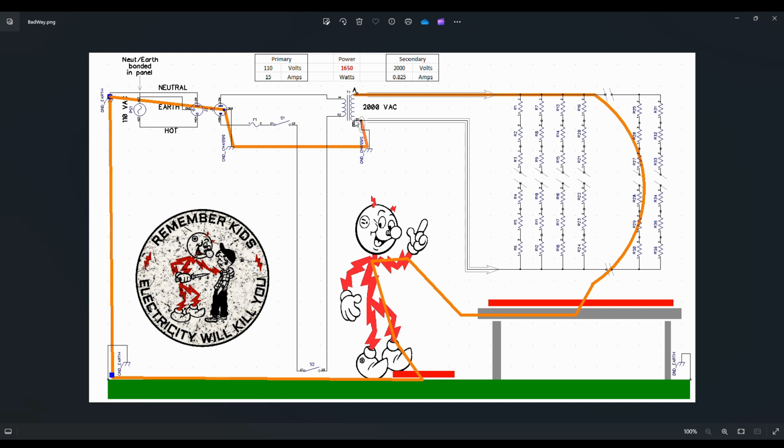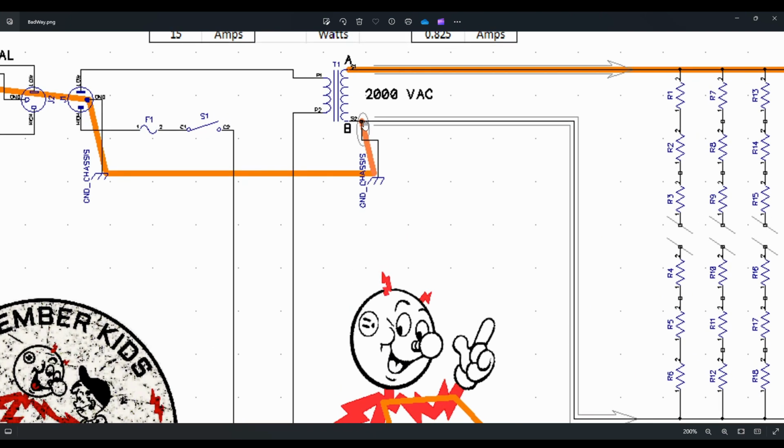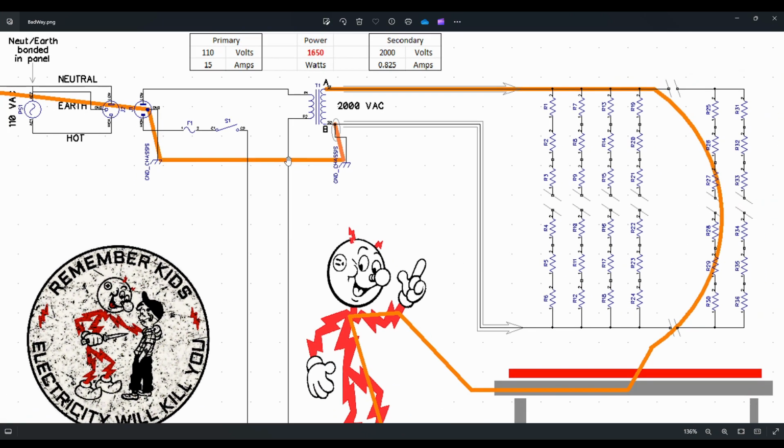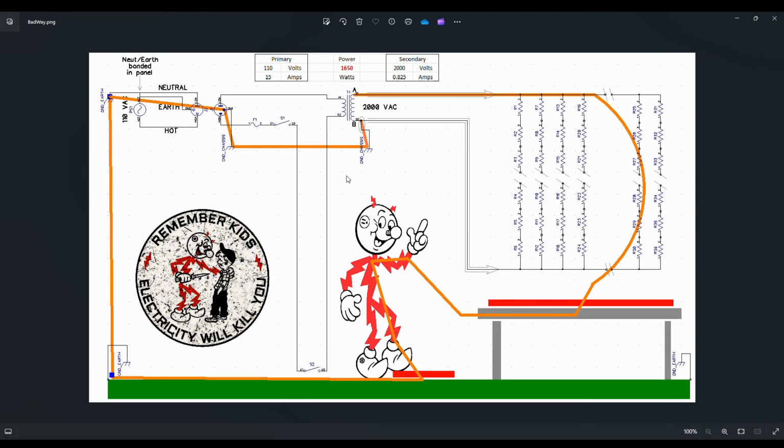It's still a dangerous situation, but it's nowhere near as dangerous as if you do have this connection to your chassis from pin B. Now I should say, there's you out there who have used a plastic enclosure, which is a very good attempt. It's not a bad idea, but if you made the mistake of making the connection between here, your chassis of your transformer, and here, your neutral coming in, then your plastic box is providing very minimal additional improvement. Very minimal, if any.